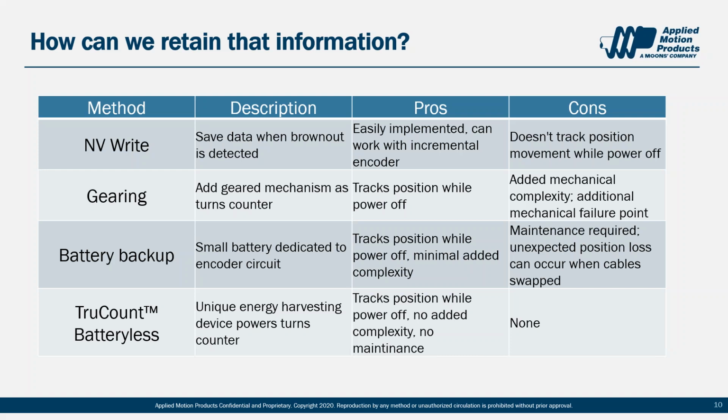With the TruCount encoder, it is completely batteryless. And the way that it works is it harvests energy on every rotation. So there's nothing in there that says after some amount of time, I'm not going to be able to harvest energy anymore. So it can be off for years, and it won't care at all.